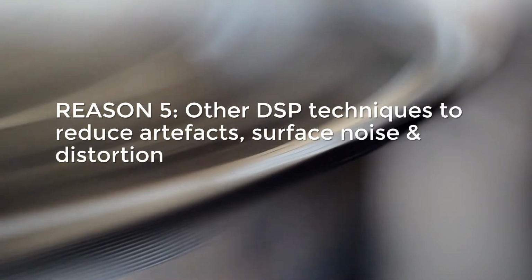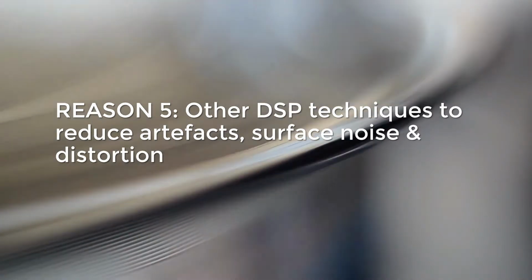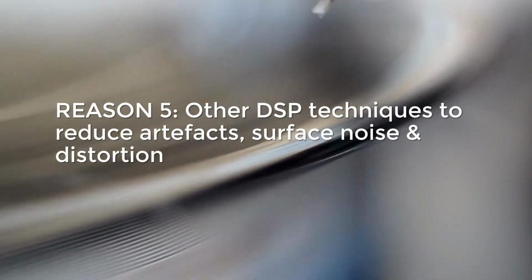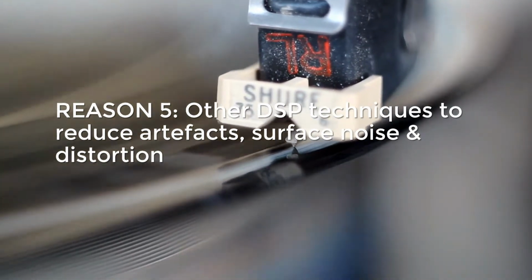Having the audio represented as data, we can use modern signal processing techniques to correct for some of the inevitable imperfections in the analog medium, including reducing various forms of tracking and tracing distortion, wavelength loss, and for imperfections in the phono cartridge which affect frequency response and channel balance.